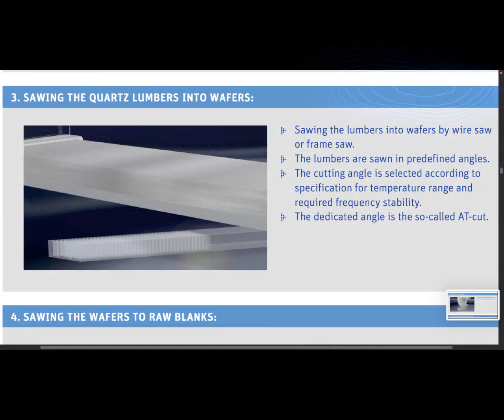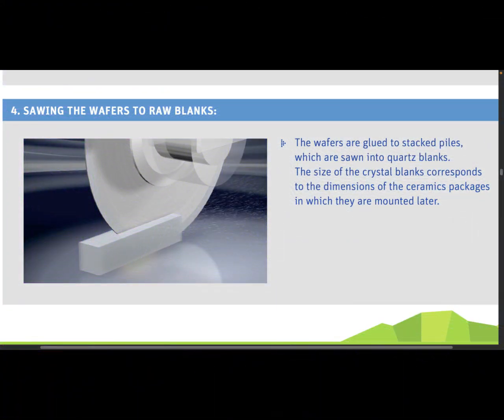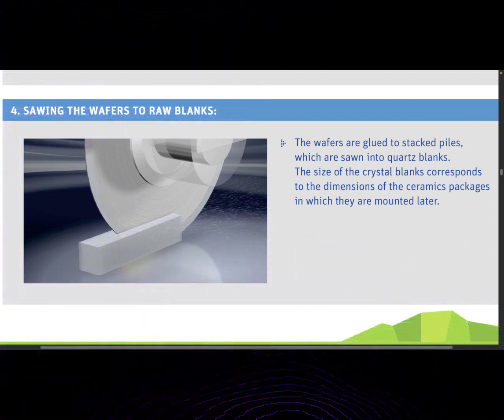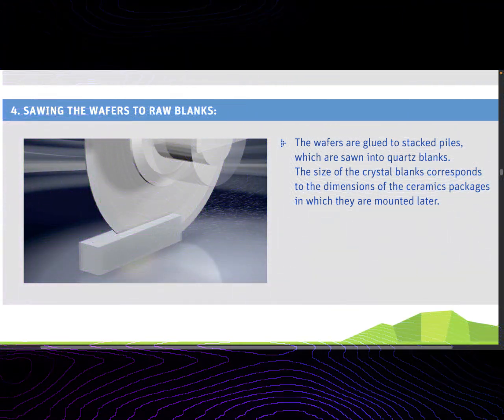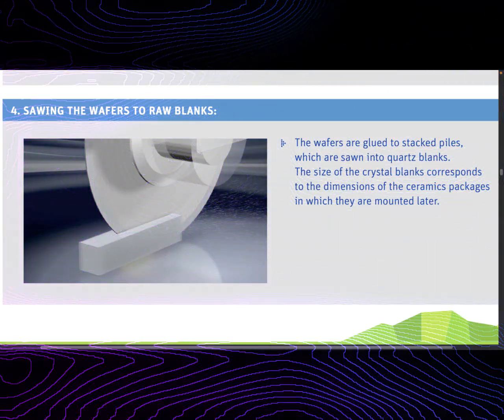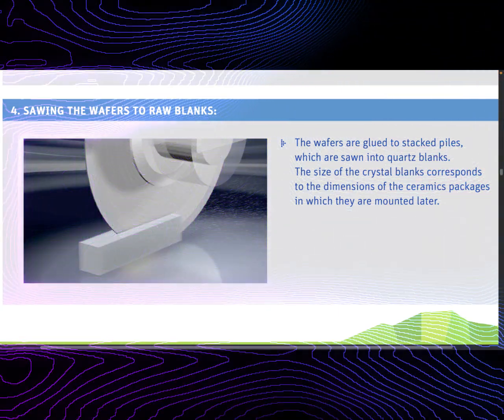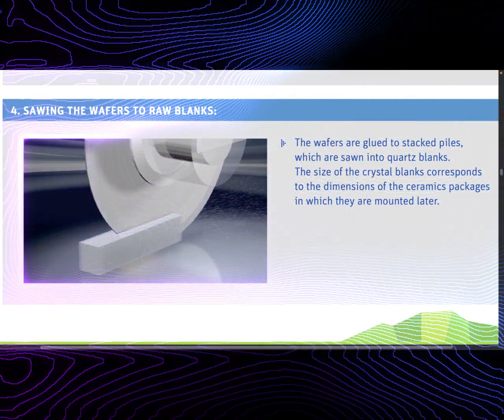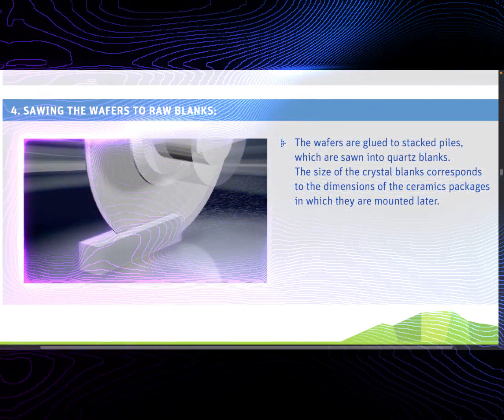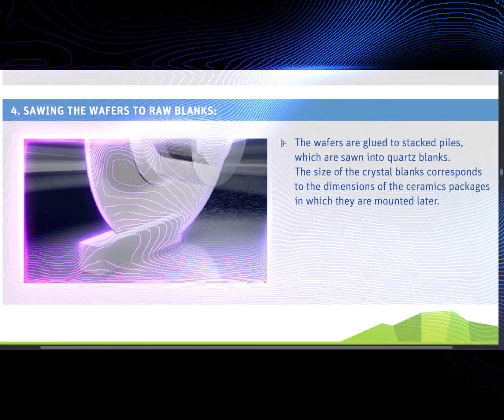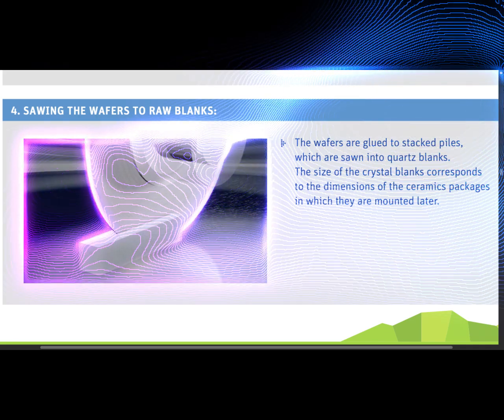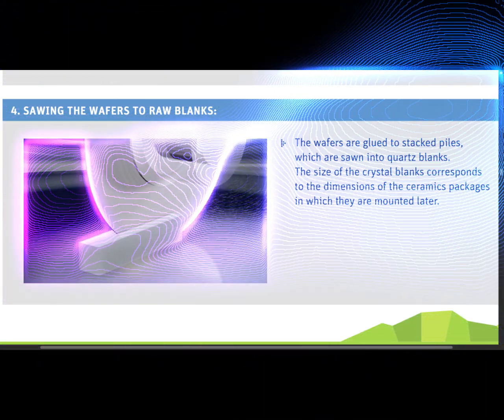Specifying and choosing a crystal. Some of the characteristics to consider when choosing a crystal are listed here; these should be defined in the data sheet for the crystal or oscillator module. Package. Crystals are available as surface mount devices, SMDs, and through hole mounted. Frequency. The specific frequency of the crystal, specified in kilohertz or megahertz. Tolerance. The allowed deviation from the nominal frequency, normally specified in ppm.